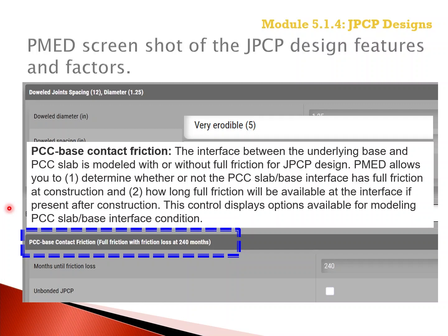The software allows you to determine whether or not the PCC slab and base interface has full friction at construction, and how long full friction will be available at the interface if it's present after construction. This control also displays options available for modeling the PCC slab base interface friction.